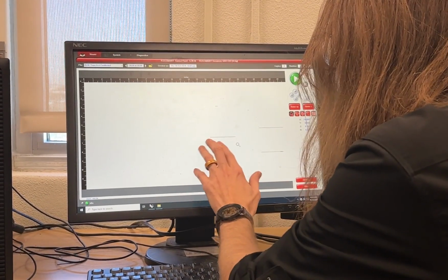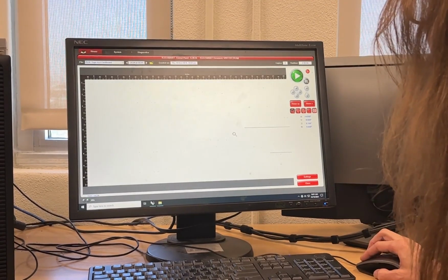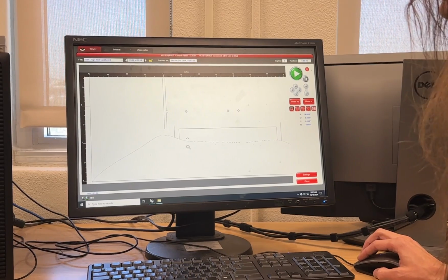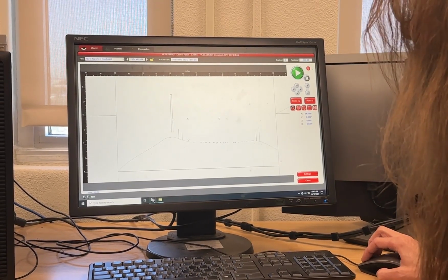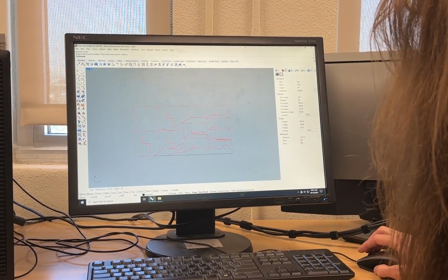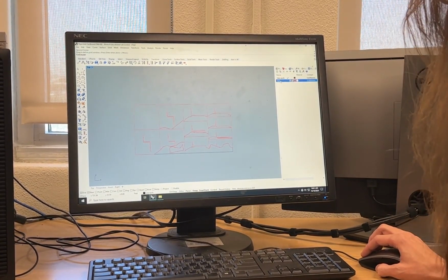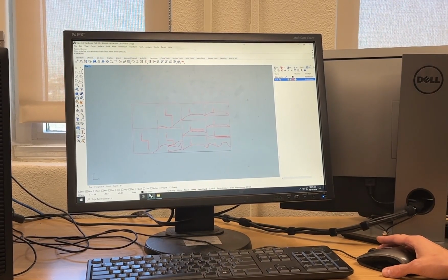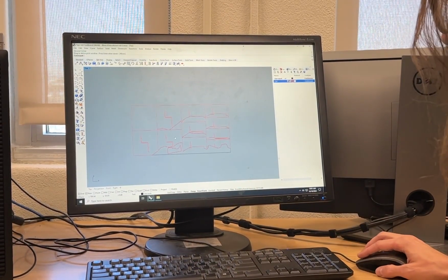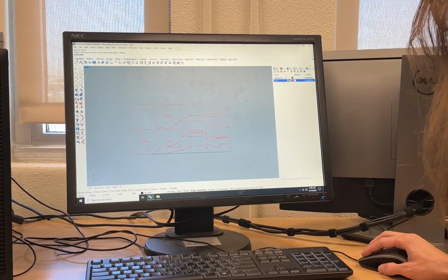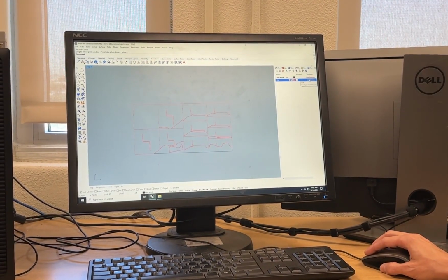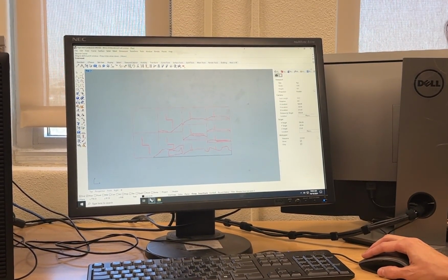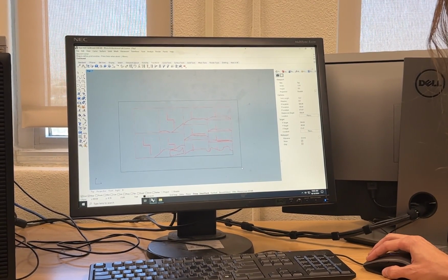And in my case, it looks like the screen's just really dirty or something. I don't know what's going on here. All my lines look a little bit funky, right? So actually, maybe I need to change something. In my layers, I forgot to tell you guys this, but we need a specific line for this printer, right? So by default, I'm going to just change everything in the layer. We do need to be continuous line type. And in my case, I know it looks a little bit different, right? We'll have to go to properties and select those lines.